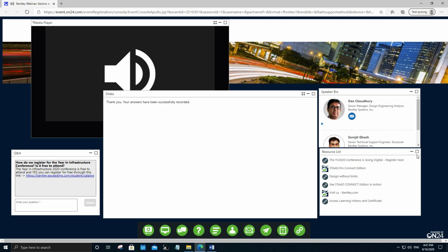Okay, Sudeep, do you want to answer or add anything further? We are done with the Q&A session. Yeah, if you're using a static seismic analysis, you can use the repeat loads. For that, you need to specify the perform analysis and change command. Though that is probably not required in the current CONNECT Edition, I'd still suggest that you do a perform analysis and change command after each static seismic load case if you intend to use the repeat load cases.